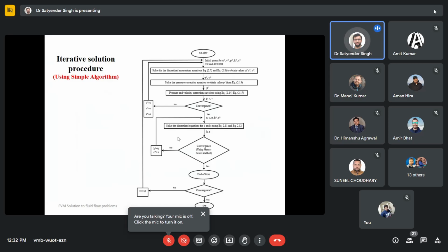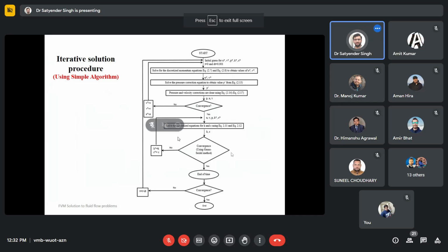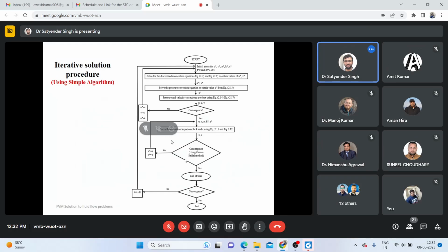You will not find any difference in the way we do it in the semi-explicit method. What we generally do in the semi-implicit method is make equations for all variables in one go, because, as I already told you, in the implicit method all equations need to be at n level. So they will be taken, and some matrix solution method like the Gauss-Seidel method has to be used, to calculate u, v, p in one go.